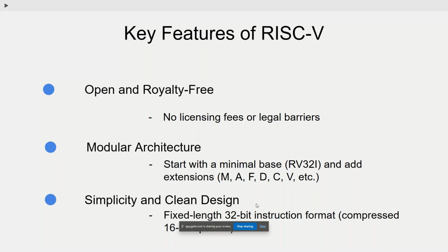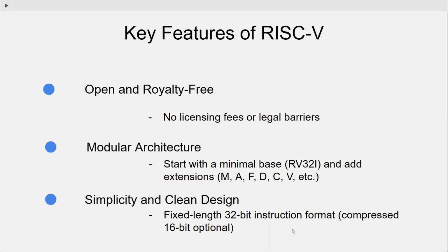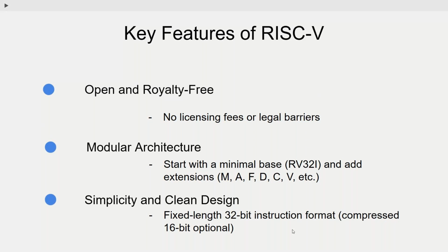Ideally, if you consider x86 or ARM architecture, the instruction length may vary. Different instructions may have different lengths. When the instruction length varies, for software it doesn't matter, since whatever the instruction is, it is going to compile. But the load of variable-length instructions falls on the decoder side, so my hardware architecture also becomes complex.